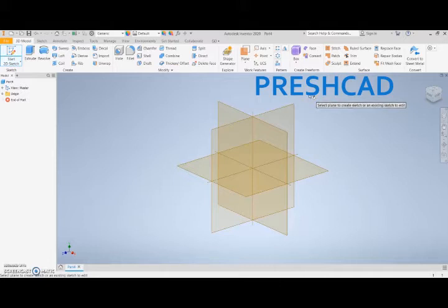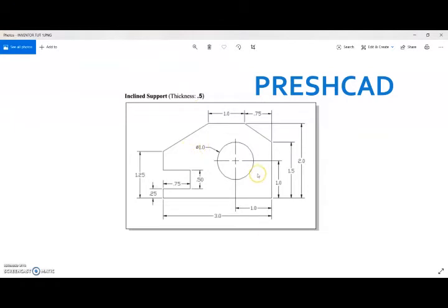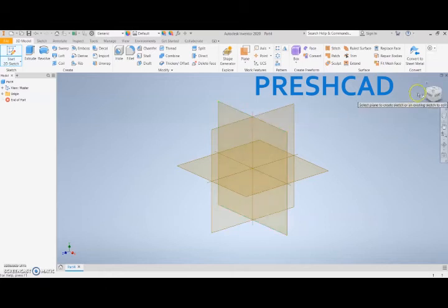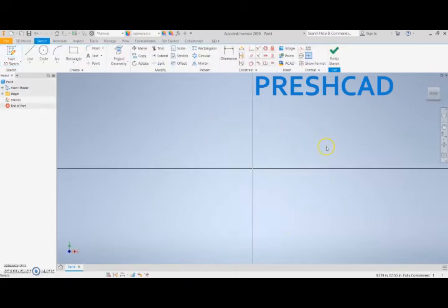Now remember I said, bear in mind that the sketch is a front elevation kind of. So that will guide us in selecting the plane to use in drawing this shape. So since we have in mind that the sketch, that's this one, is the front elevation, that will guide us. So opening Inventor, we can look at the plane, XY plane, front. So it's simple. So let's get into the sketch.